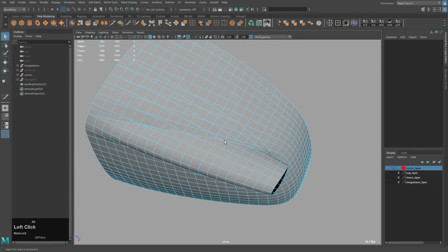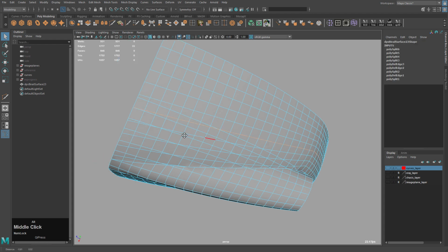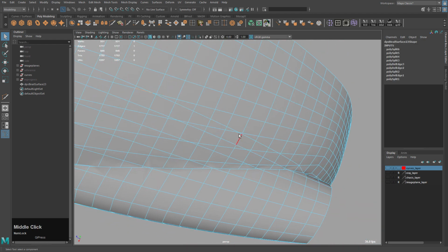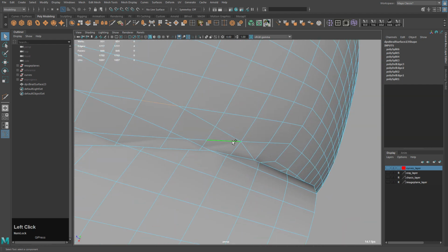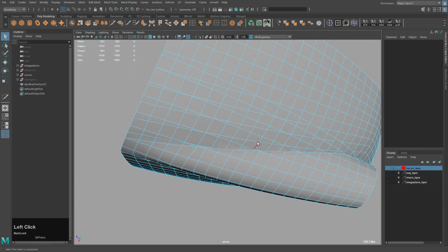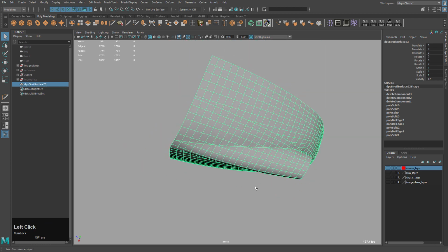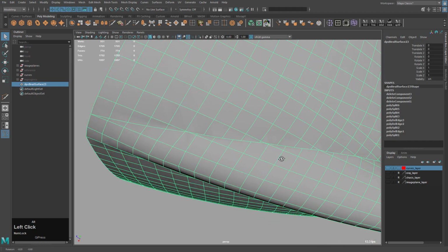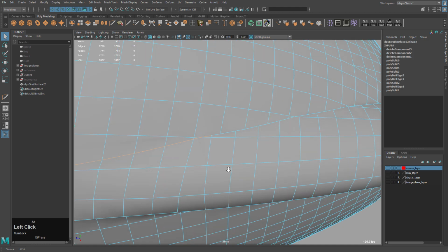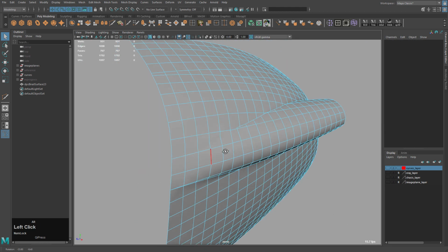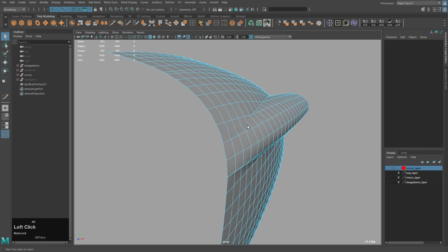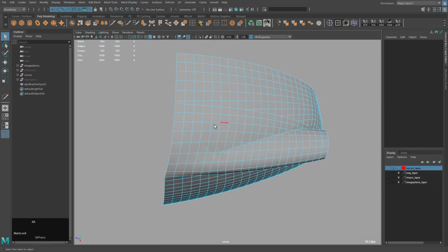I want to delete some of these diagonals, and if I just double click, it's going to select the whole edge. So I'm going to go along this new edge and delete any of the diagonals that are trying to cross, like this. I'm just pressing delete, not control delete. I want to keep the vertices just in case the shape's not going to be right. Okay, now you can see we can delete this one, and that's what we're going for. We have these vertices here, but once we delete them, this will smooth out. But that's the idea. See how we're drawing it?